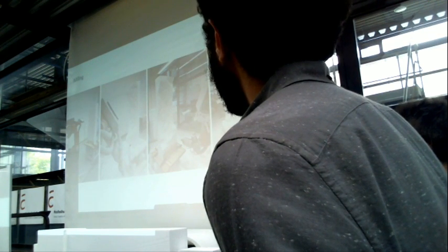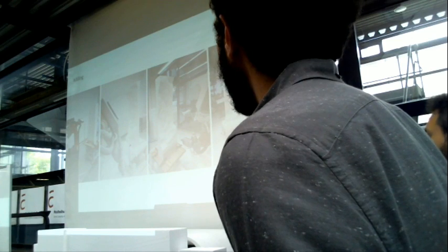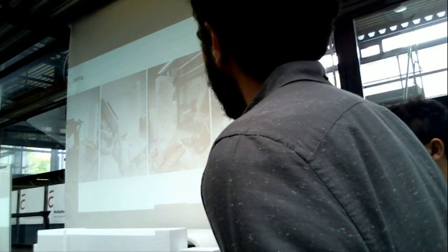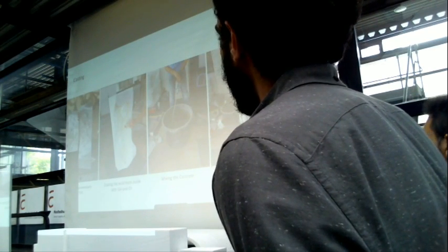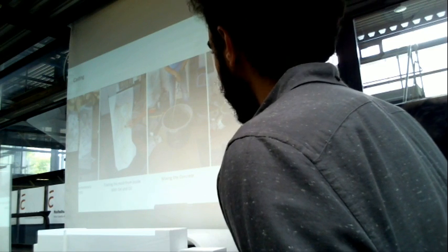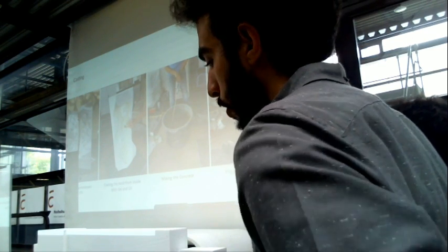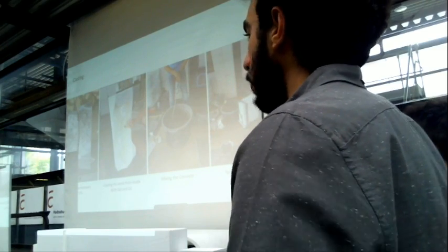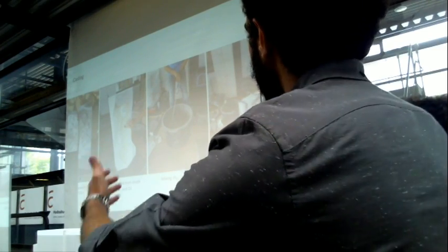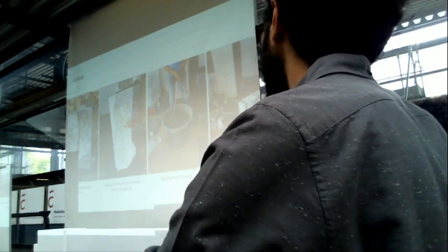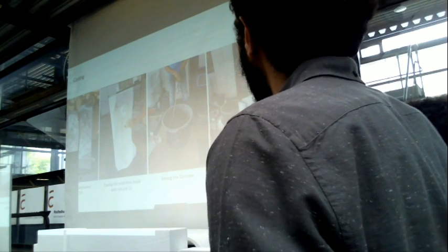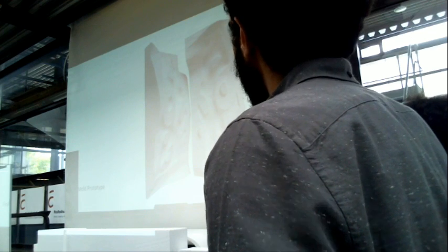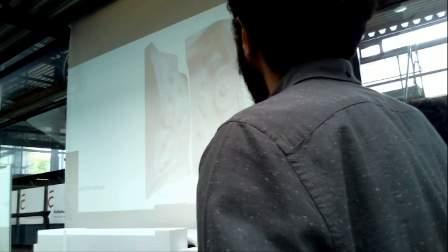So coming to actual construction, we have started doing the molds through milling, and by the way that we have explained before, through 4 components. And then after the milling, we have taken out the molds and properly sealed them in order to avoid any leakage of concrete inside the foam, so it wouldn't stick when we remove the temporary molds. And these are pictures showing the process of preparing the molds and then mixing the concrete, and then the final closing sealing of the mold and casting. And this is the final mold prototype that we have used.